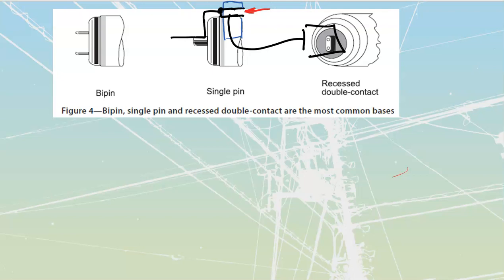A couple ways that they could deal with that. One of them was going to be a lead lag ballast. That was going to have two lamps inside of there. One lamp would come on first, then the next lamp. So they'd be kind of alternating back and forth like that, which meant that we always had one that was going to be high.